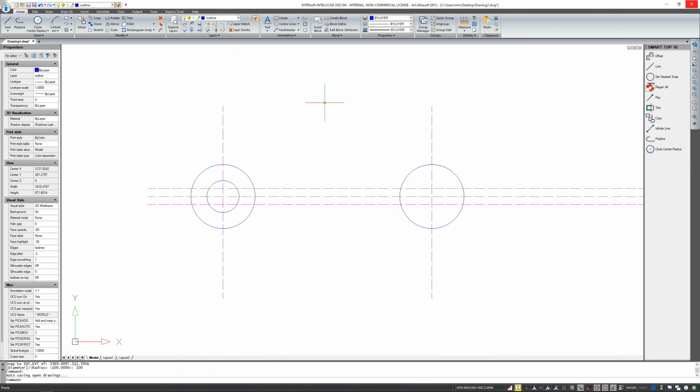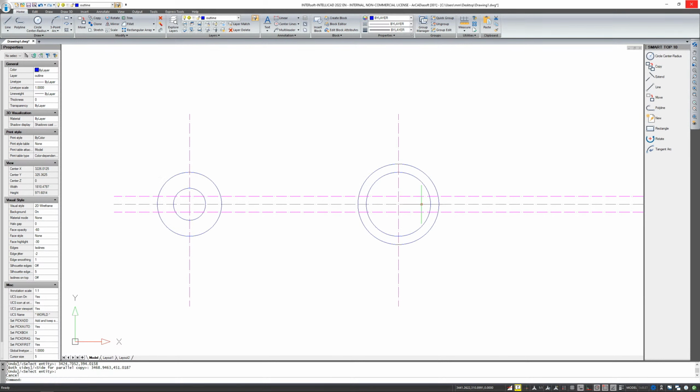But I can also use the offset option for that, which I have already shown here on the line and the rectangle. I choose only the distance, say 26 units, confirm, and show which way. So this offset can be both to a straight element and to circular arcs, to all elements that are in the program. When you edit an element, copy, offset, rotate, they always take over the properties of the element from which you are copying. I'm talking about properties like line thickness and belonging to layers.